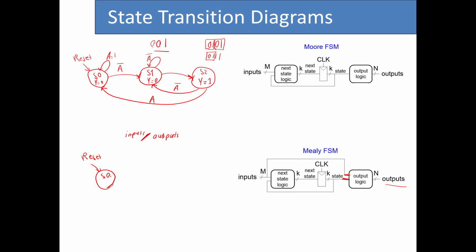So now let's just say we are at state 0, and again state 0 is representing that we didn't detect any part of the pattern yet. So what happens if we detect a 1 as the input? Same as above, we stay in the same state. So here A is the input, representing that the input is 1, and Y is basically 0. So I can just show it like this: A/Y bar. Or since we only have one bit, I can just show it like this: 1/0.